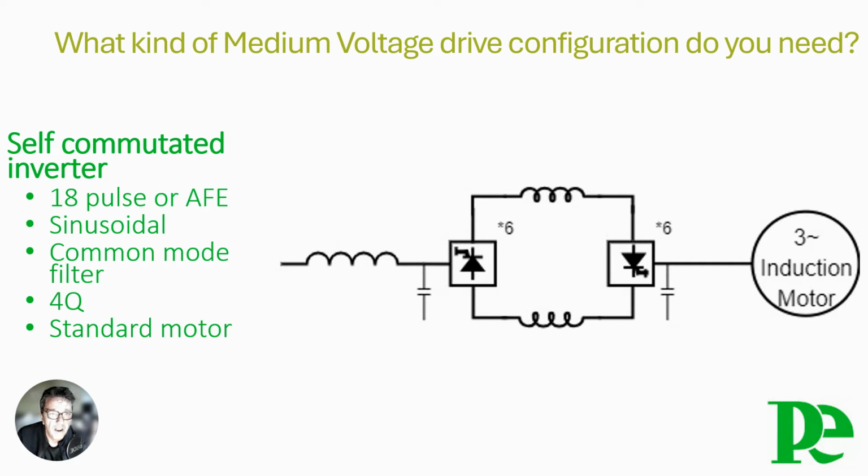These benefits include attenuation of the effects of transients on the grid, offering flexibility in selecting the supply voltage for the drive and the motor, reducing the maximum short circuit capacity, and enhancing system protection by isolating motor grounds from the main power distribution system.